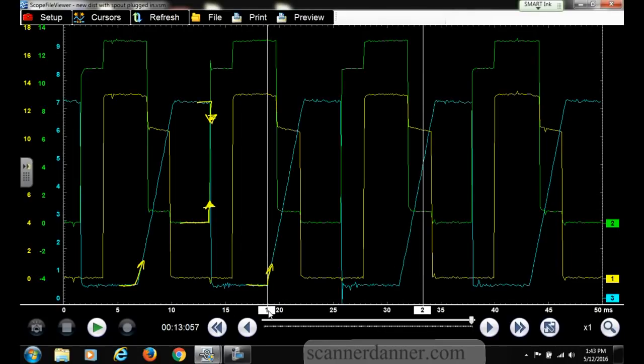Can you see how the turn on of the coil doesn't really correspond to anything in the yellow trace or the green trace? Can you see that? But the turn off of the coil, which would be this area, remember the blue trace is my coil current ramp, the turn off corresponds with the spout increasing signal. Anyway, that's why I didn't mention it in the last one, is the dwell time. When to turn the coil on, I don't see a clear indication of when they're doing that.